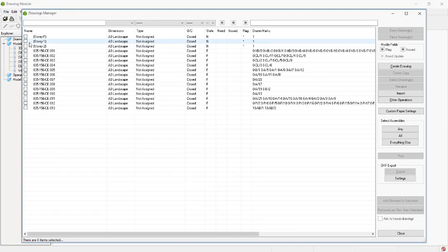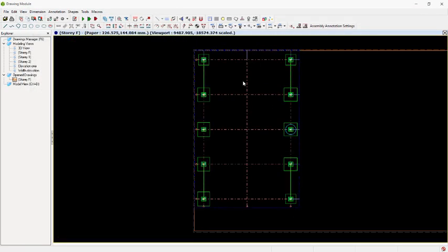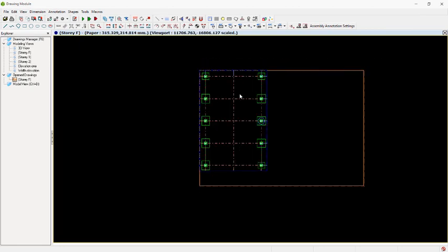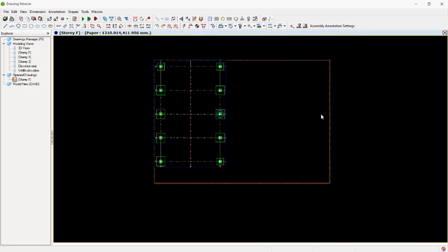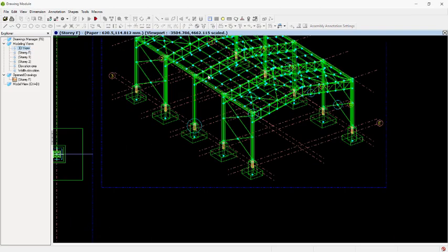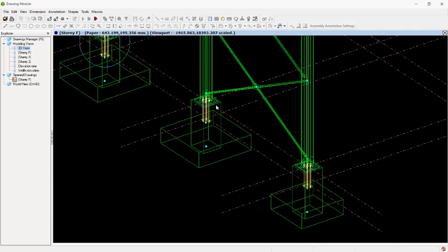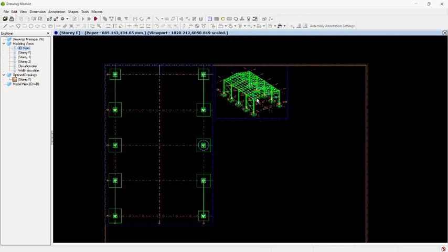Before we actually export those drawings, we need to get to the floor plan of this particular structure. So double click here, and close this. Here is the foundations level. In this foundations level, we need to create the sections that we created, using the section box. Before you can do that, you have to activate the 3D. So right click and then create 3D view here. This is the 3D view of the drawing. This is the same thing you are seeing in that template that I've shown to us. Just like this.